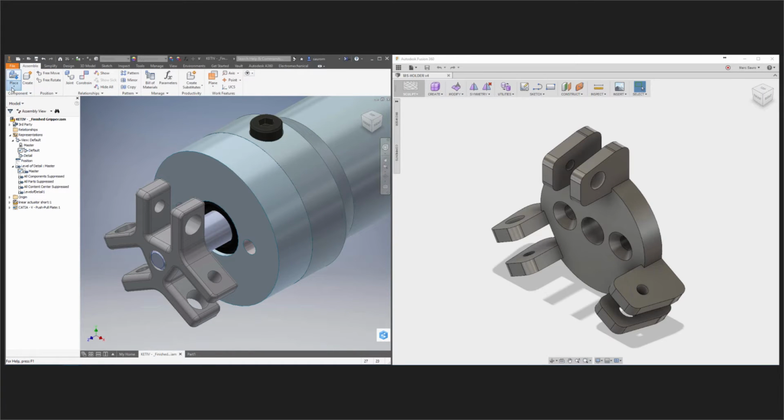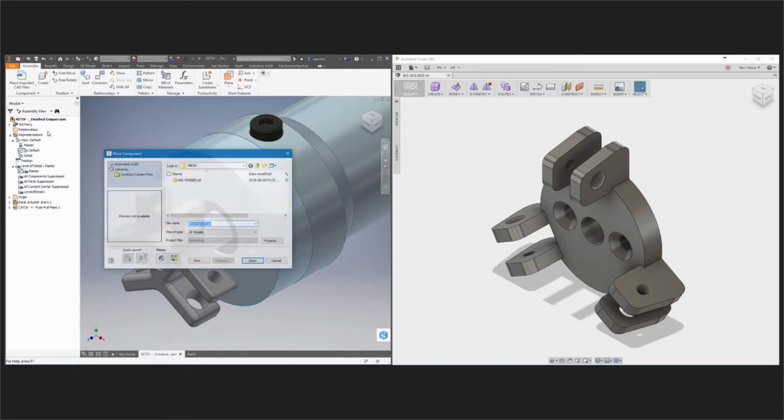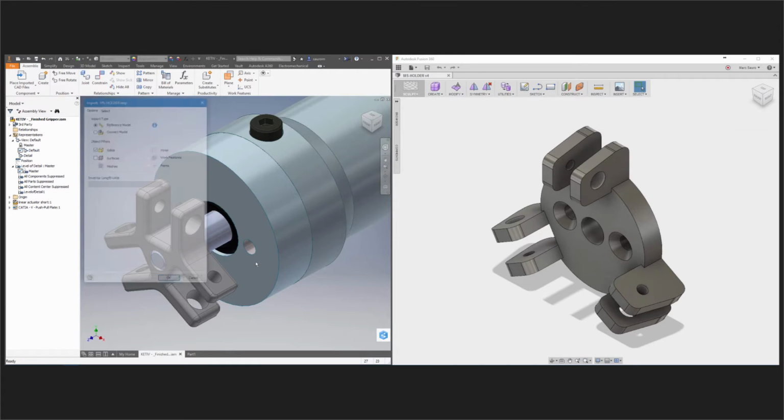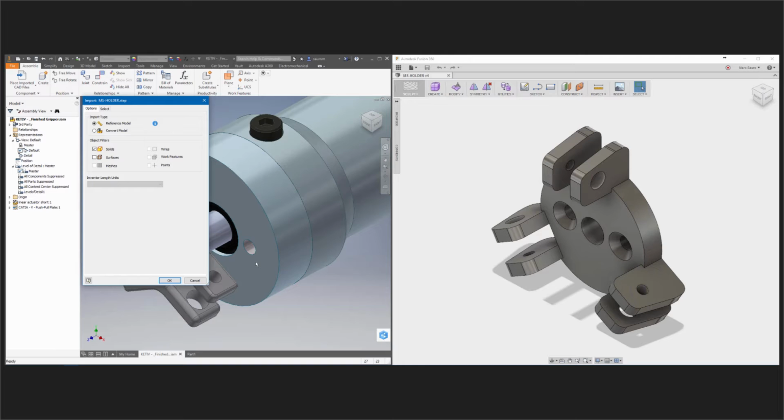so you could be in your Inventor assembly. I'm going to be placing this CAD file. I'm going to place an imported CAD file. Now look at this. I'm going to go into my step folder right here, taking this part, and I'm simply going to click Open. This is how you import AnyCAD data. You see, we can convert the model, which is all good. We all know about this. Or we can have a reference model. I don't know if you see this, but the icon is so bang on. It's a link. It's a chain, which means if the STEP model is changing, my assembly will change as well.